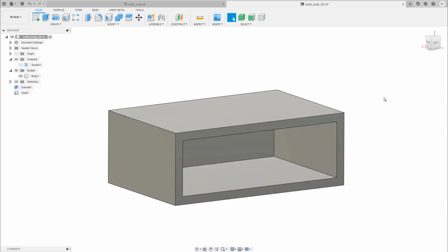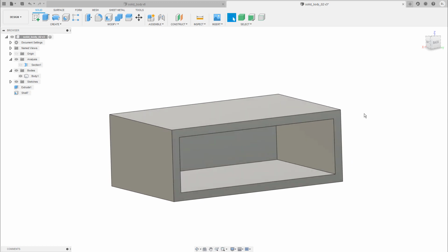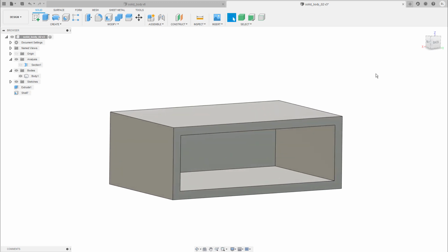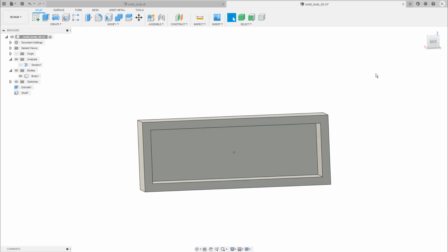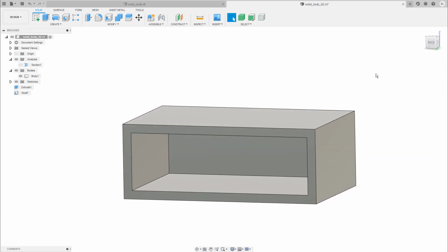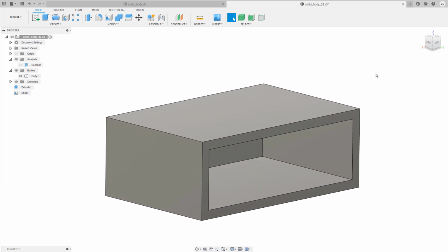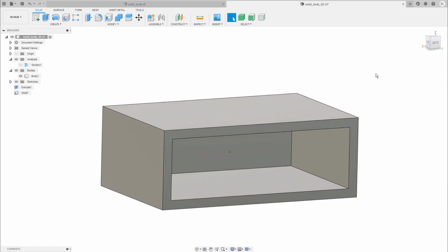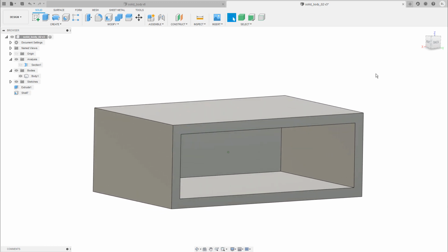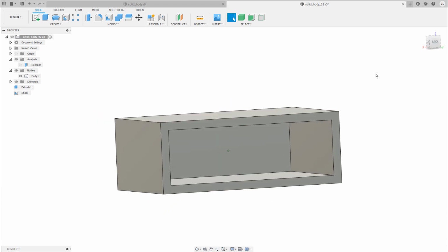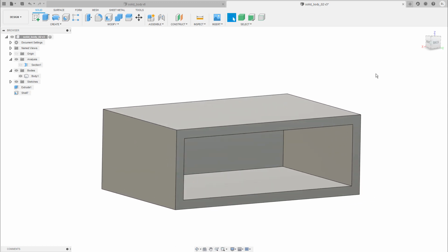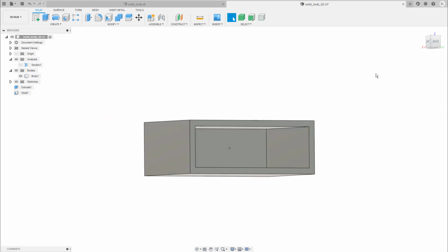When you do not have any previous experience in other CAD applications, then you might think that this behavior is standard, but I can guarantee that it's not. It makes the entire modeling process a lot more straightforward, a lot more intuitive, and it's also a huge relief when you have to deal with surface models and solids that you import from another application. In this case, the parametric history is missing, and you had a hard time making adjustments on the model. So sometimes you had to reverse engineer the entire part to make it work. But in Fusion 360, you simply grab the faces, move them around, delete them, add additional parts, and you can do all of this on the fly.